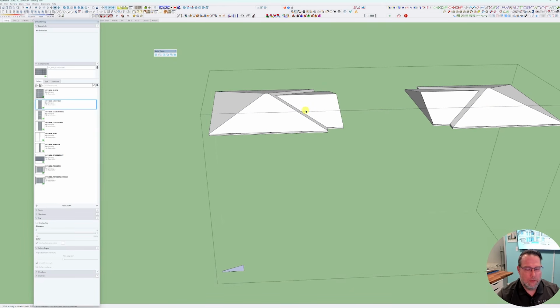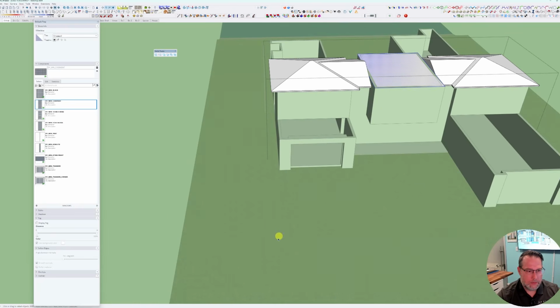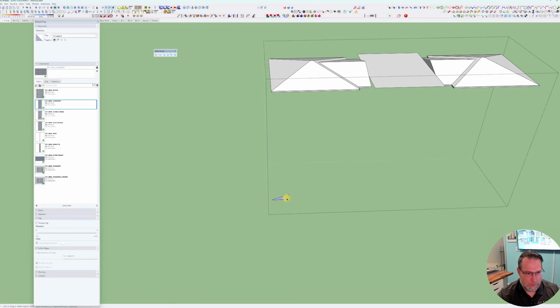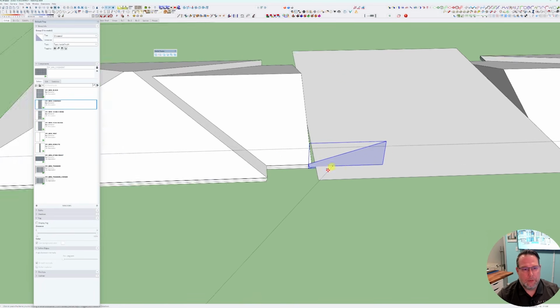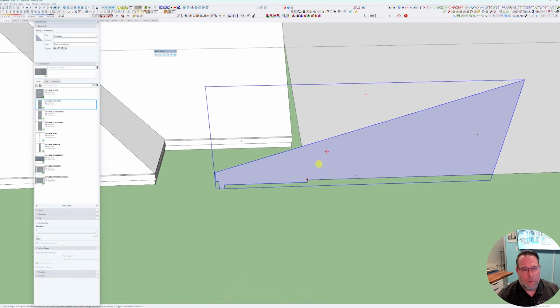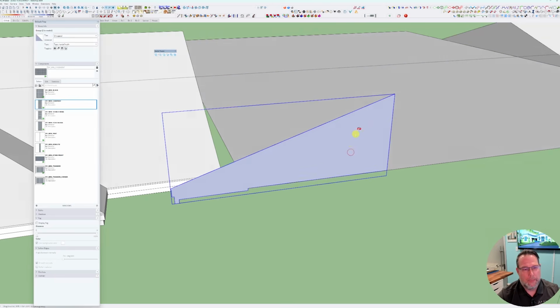And to get into the roof, we will draw this outline, because I need that outline. I'm going to turn this guy into a group and select by my insertion point. The reason I turned it into a group is that I didn't want this geometry to attach to this geometry, because this is loose right now.